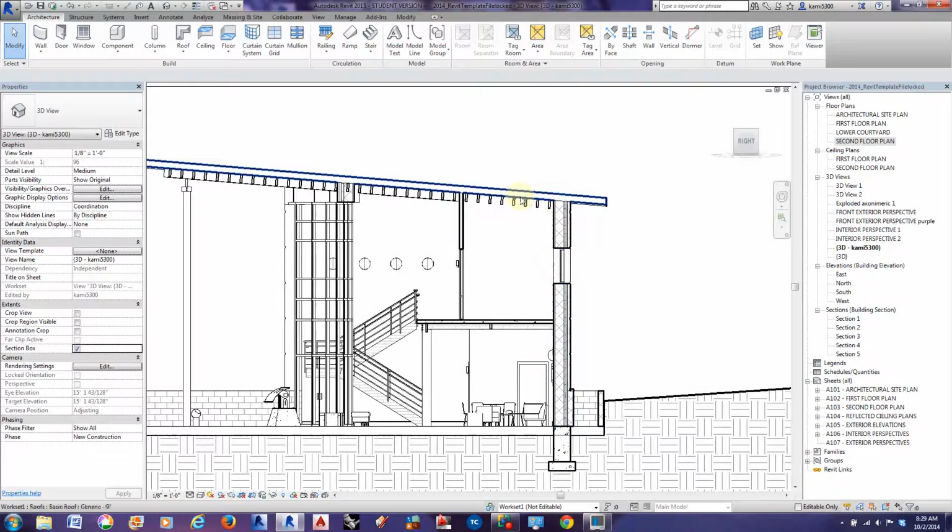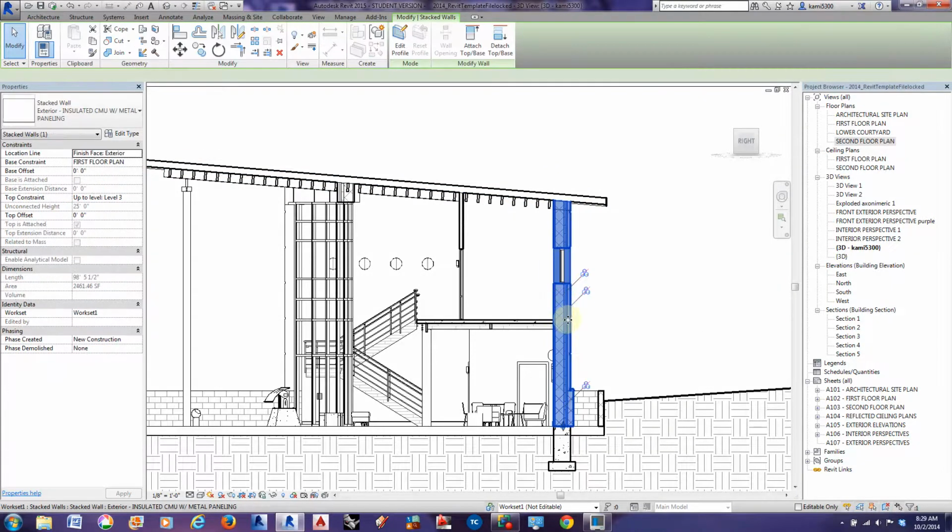And just to further emphasize that, you want to think about the thickness of your materials when you go to laser cut. So, for instance, it wouldn't be appropriate to cut this exterior wall out of chipboard. And in fact, when we exported them, it shortens the wall a little bit because it's connected to the east and west wall. So you want to think about the thickness of the material.